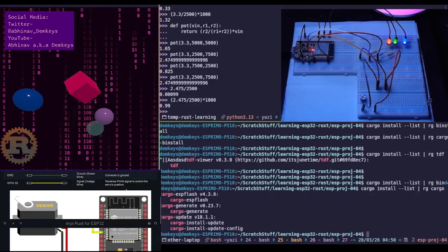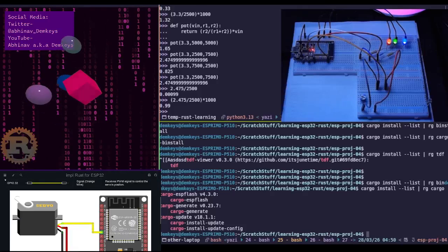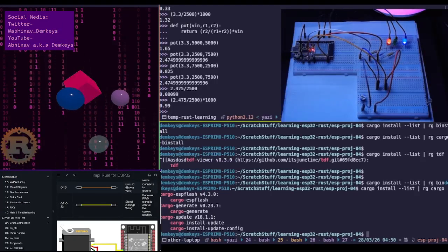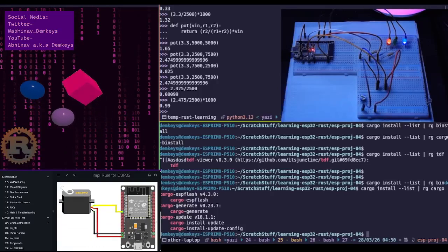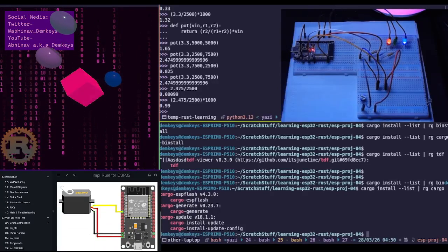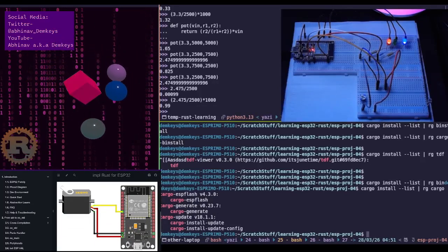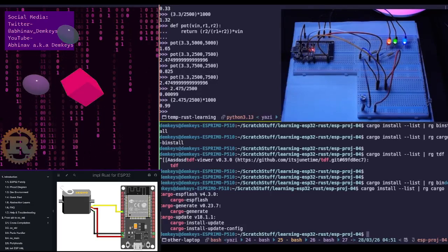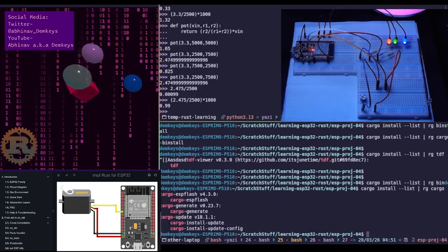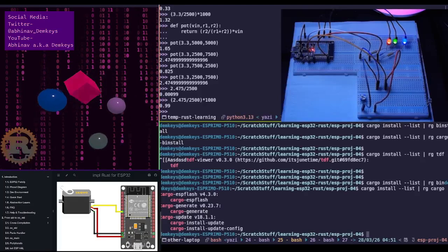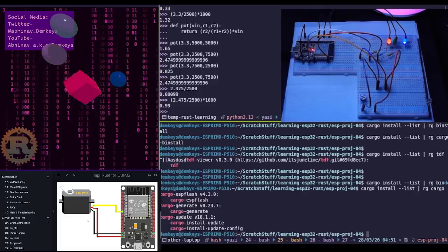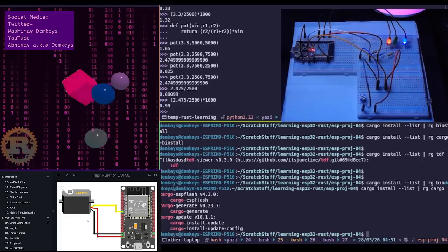So yeah, I need to do some research on this and see how safe or unsafe it is to plug the thing directly into the ESP32. I did notice that we are giving it 5 volts, so we are connecting it to Vin rather than 3.3. 3.3 is what the entire microcontroller is operating at. That's the voltage range that the microcontroller is operating at.